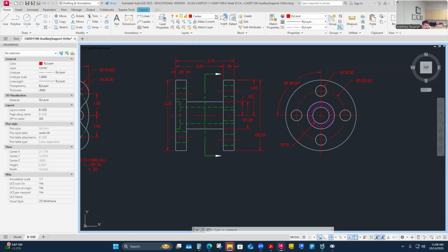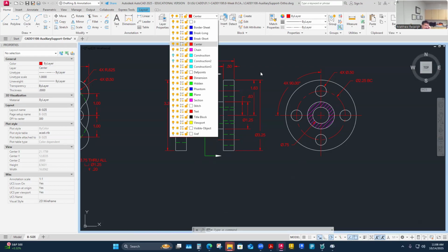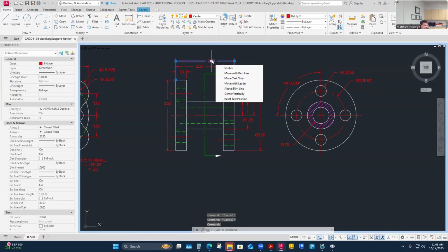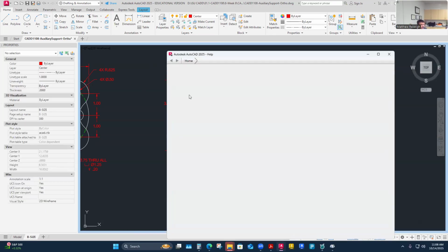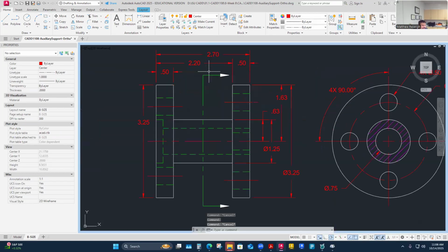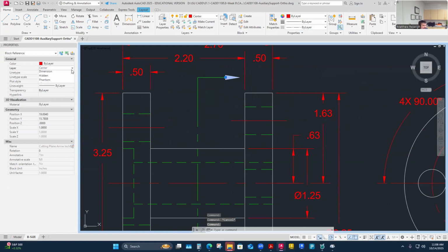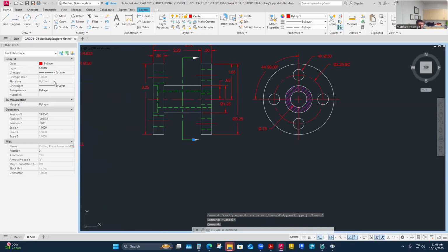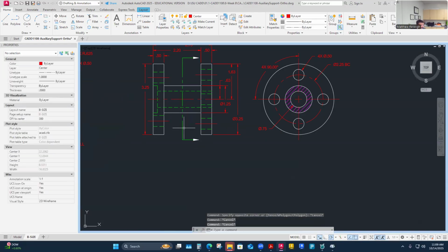So I'm going to go to my text layer, and I may have added all those dimensions on the wrong layer. So I've got to double check that. Don't do what I did, but I probably did put all these. No, no, no. Every time I'm pulling a dimension, I'm on the right layer. It's just that I probably put this on the center layer, and I think I'll just move it to the visible object layer. Even though I created that with a visible object, I could choose to put that on any layer essentially. So I wasn't watching myself and I'm on the wrong layer. So visible.